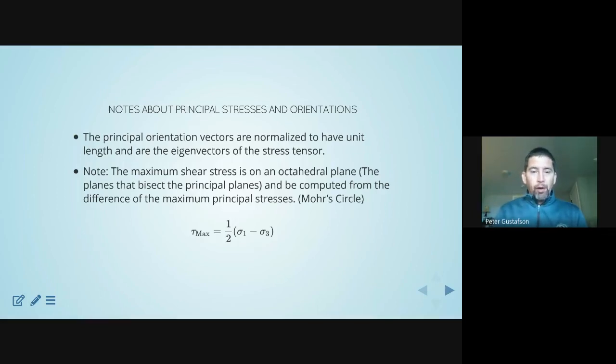So what we computed were principal stresses. By definition, as you saw, those are the normal components of the traction vector in orientations where the shear stress was 0. So what we found was the maximum value of the normal stress, and the minimum value of the shear stress.